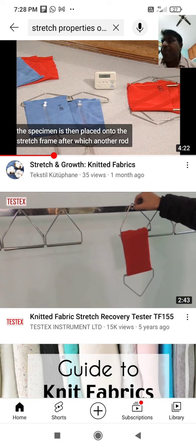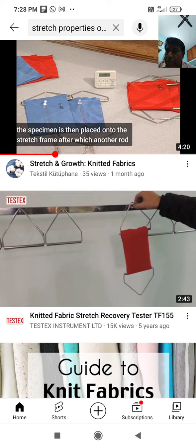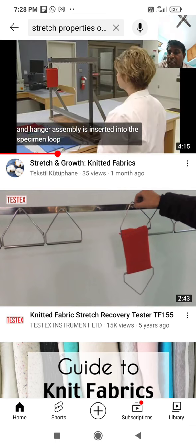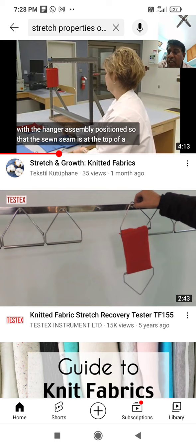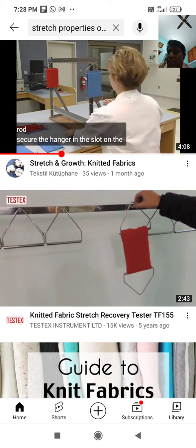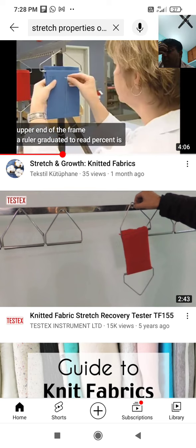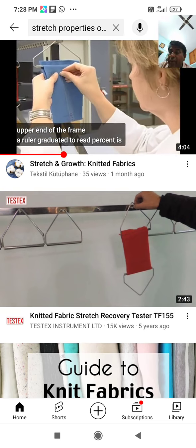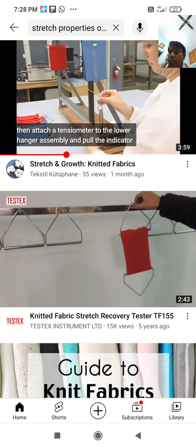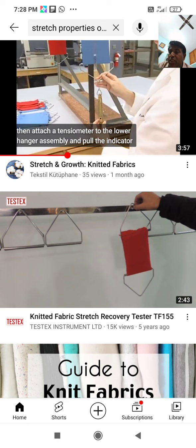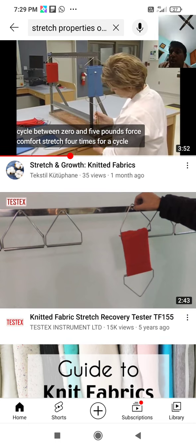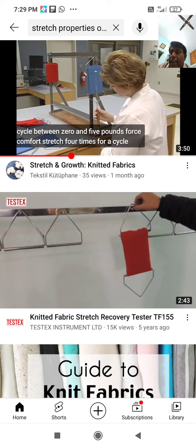So the problems associated with the above fabric are these. Puckering may be due to differential shrinkage or localized delamination in very small areas. Crack marks are usually the result of combining tight fabric constructions, at least one of which does not have sufficient residual stretch to allow the combined fabrics to be bent in an arc without producing crack marks.